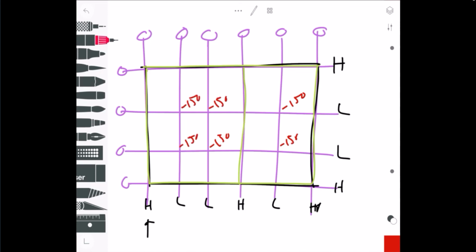Those are going to be our low points where we drop the structure down. And so what we end up with here is a sloped roof that looks like this now. So again, what that means is that this beam here is at a high point there and a low point there. This beam here is at a high point here and a low point there. And so this middle beam is at a low point and a low point.